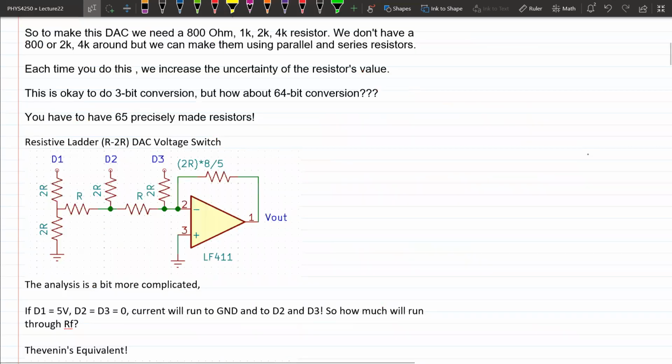This is known as an R2R ladder, where, let's say you're trying to do an 8-bit digital to analog conversion, right? You actually need 9 different resistors that have the exact right value. And as you see in the lab, you don't usually have 8 different kinds of resistors. So what this allows you to do is only have basically 3 different resistor values.